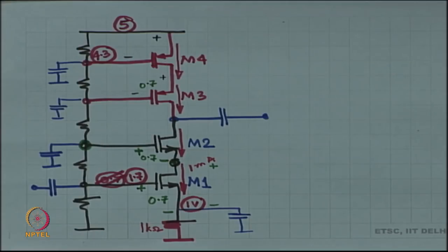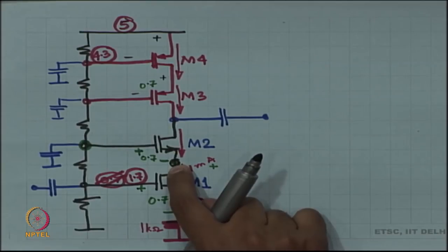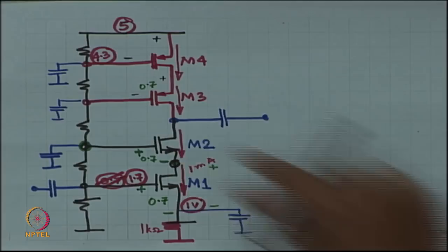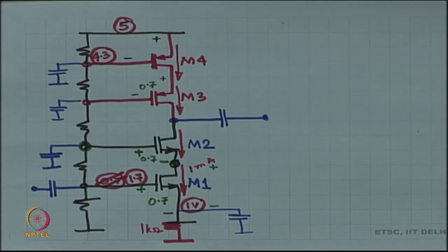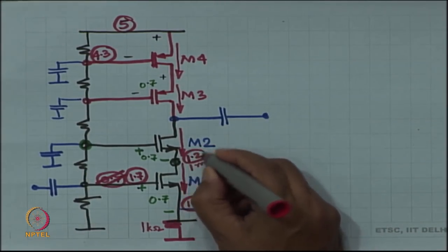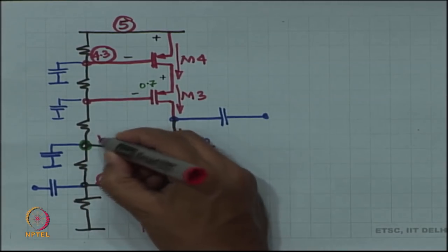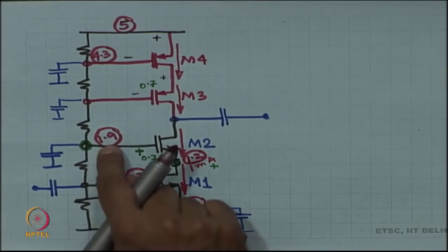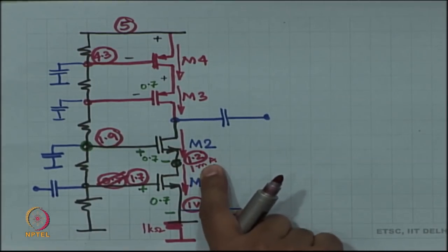Is that understood? Great, because this voltage is not swinging either, it is pretty much static. So, 1.2 is actually fantastic, because that gives you the largest headroom across M2. I would like to place this node at 1.2, which automatically means that this node should be at 1.9. Now, when I do the resistive divider and place this node at 1.9, then automatically this goes to 1.2.